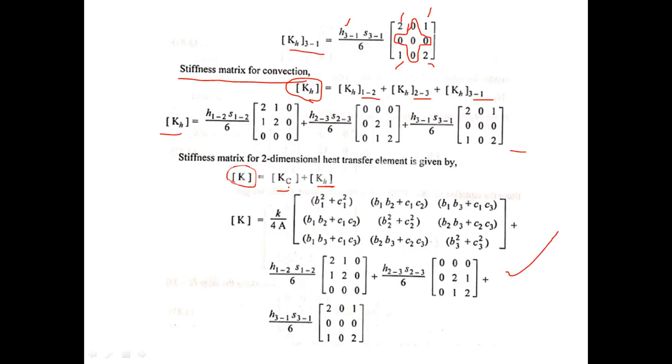Thank you. In the next discussion we are going to discuss the derivation of the force vector, that means the load vector F of the heat conduction. Here F1 is equal to Q naught integral of N transpose dV, that is the equation. So here we are applying the shape function values, and as usual we are solving it throughout the problem. Over here we will get F1 equal to Q naught A divided by 3 into the vector 1 1 1.